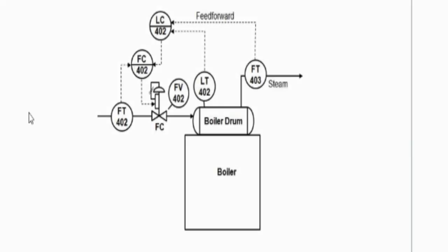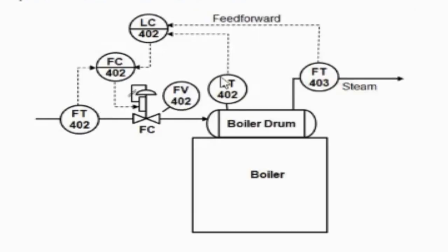This is the piping and instrumentation diagram of boiler drum level control. The 3-element method is nothing but having 3 transmitters with 3 measurements: input water flow, level, and output steam flow. This is actually the most efficient method to control the drum level. See, the cascade control structure is over here, having 2 measurements to avoid the disturbance. Then we have to measure the manipulated variable, also including level, which is our control variable.